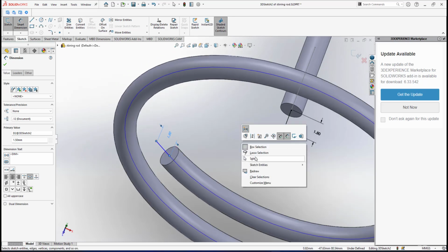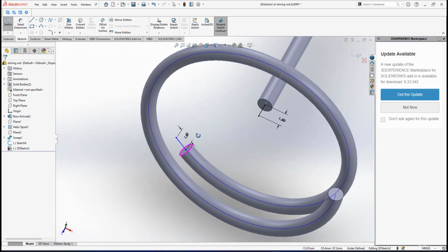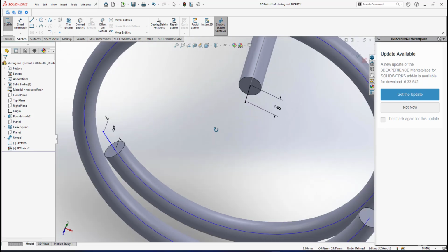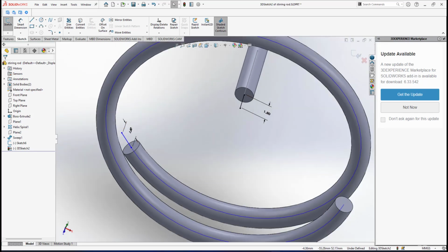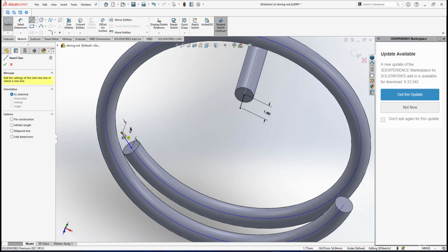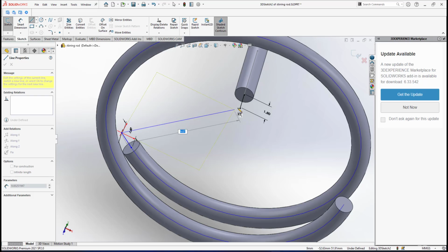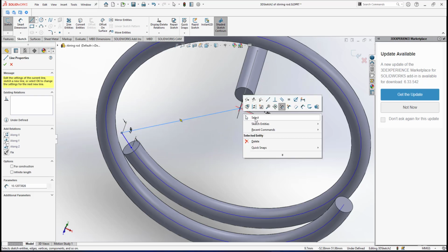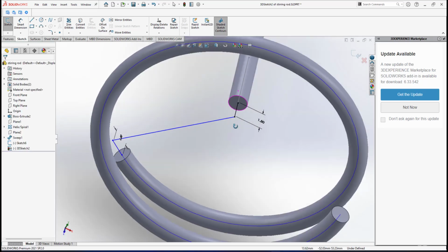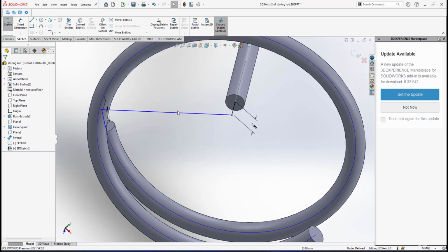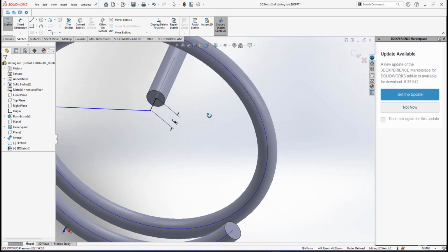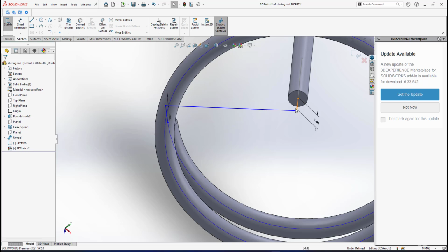All right, so 1.5 there. So here, then what I will do, I will create a 3D line also from this point to this point. Here under the sketch, I'm still under 3D sketch. I will create a line starting from this point and joined to that point. Right, so I have this line. Okay, this line doesn't have to be fully defined, as long as I have the path for me